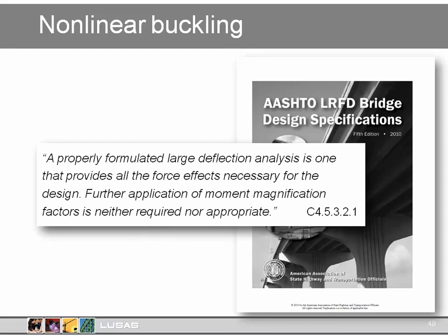That's not to say that you should omit to have a factor of safety. Of course you should include load factors in the analysis, and you will need to make a suitable assessment of material strength factors and so on. But if you have done the nonlinear analysis, you do not need to apply additional magnification for moments based on code rules.